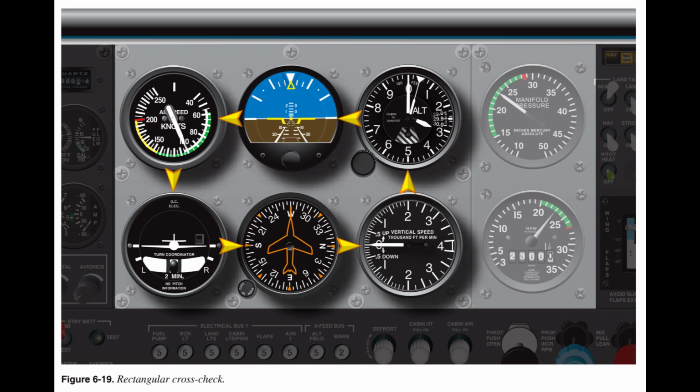Since the aircraft is turning, there is no need to recheck the heading indicator for approximately 25 seconds after turn entry. The problem here may not be entirely due to crosscheck error. It may be related to difficulties with instrument interpretation. Uncertainty about reading the heading indicator, or uncertainty because of inconsistency in rolling out of turns, may cause the fixation. Omission of an instrument from a crosscheck is another likely fault.